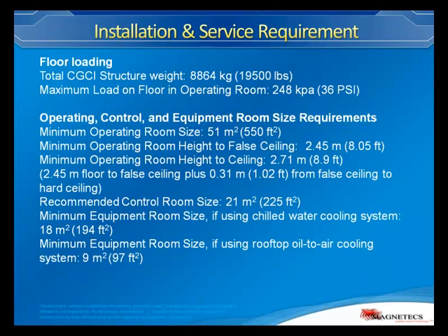Just to demonstrate, 3 grams of tool within the human body will require 20,000 pounds of equipment and roughly 50,000 watts of energy just to drive 3 grams of magnetic pellet within the human body, because of the inverse law. And of course, the size is human: pole to pole, for inserting a patient, requires roughly 650 millimeters between poles, because the FDA mandates that a 300-pound patient must be able to go into the MRI bore, and similarly for our equipment.